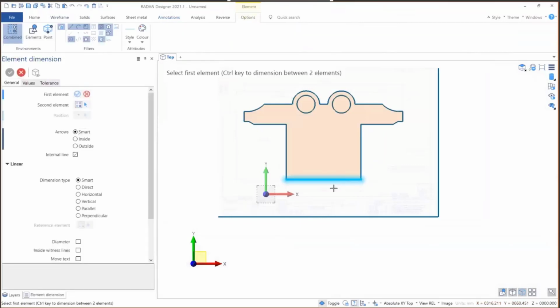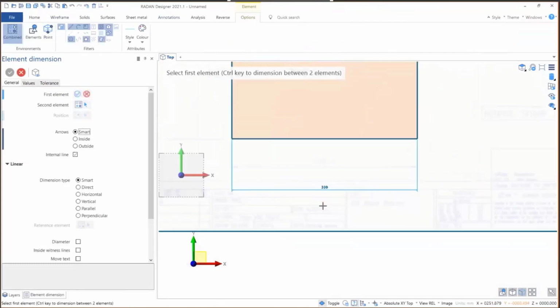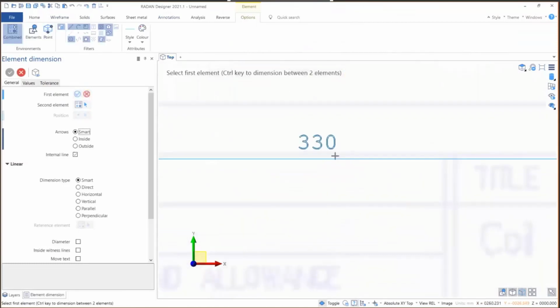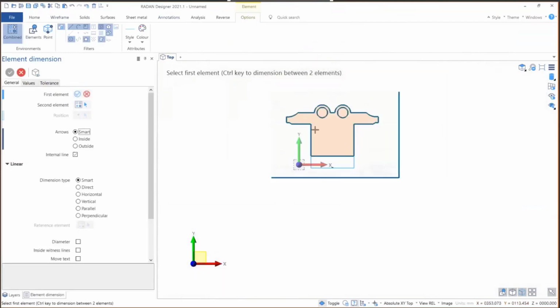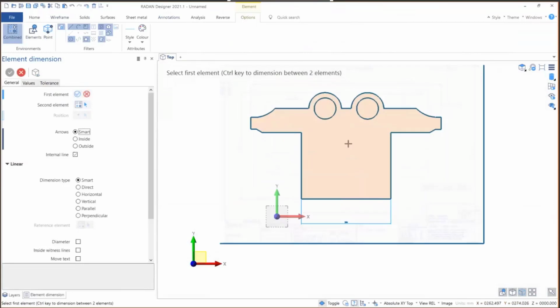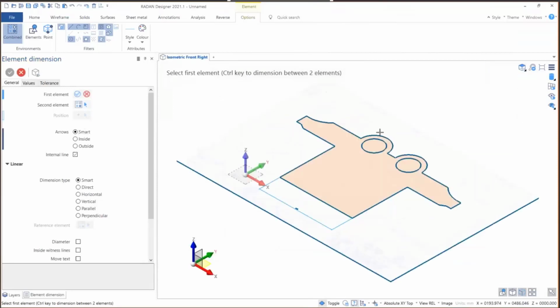So if we highlight that and put a dimension down there, look at that. Even rushing, I've been able to generate a part that is the correct size and shape that came in on an image file. The more time you spend on it, the more accurate it's likely to be. Again, I'm not saying that that replaces accurate engineering drawing. It doesn't, but it does get me to something that I can perhaps extrude to create a solid, maybe to calculate weight or volume or do some nesting on it.